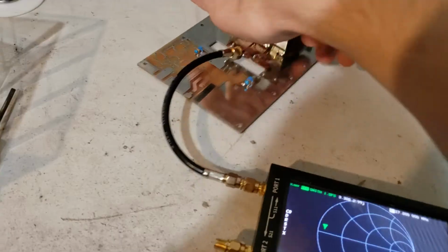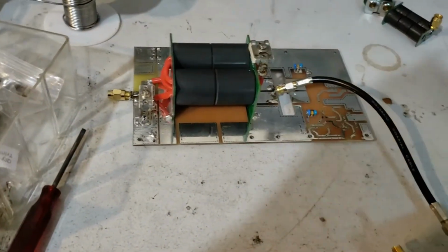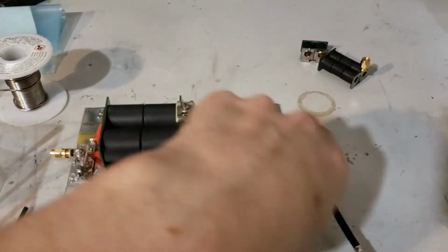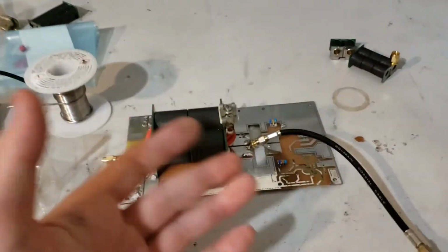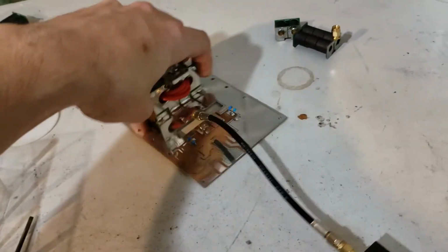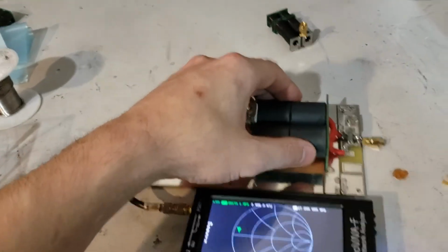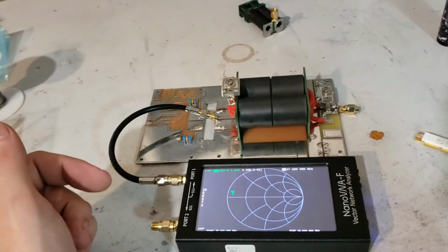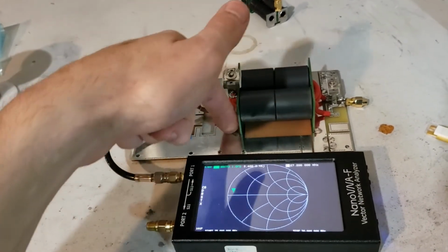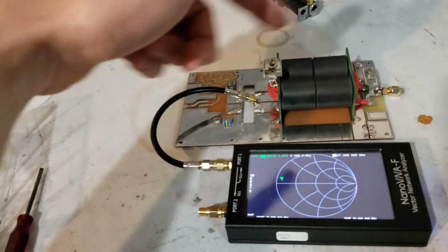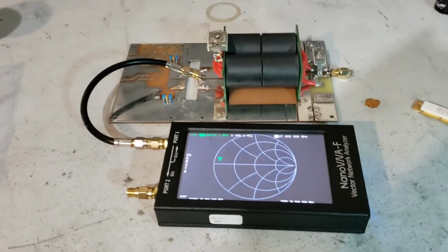So, here. Look at that big old input transformer. So we plug our radio in here, it goes into the transistors, and then we have another transformer on the output. It's basically the same thing. Now there is a difference in your testing method. So when you're just getting your impedance in the ballpark of where you want it to be, the method is exactly the same. You connect your VNA to where the transistors would be connected, and then you run that into a dummy load. So that works both ways for the input and the output.